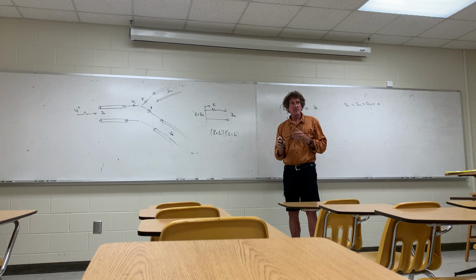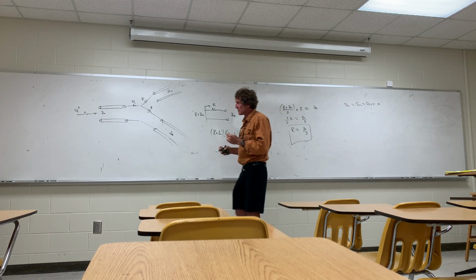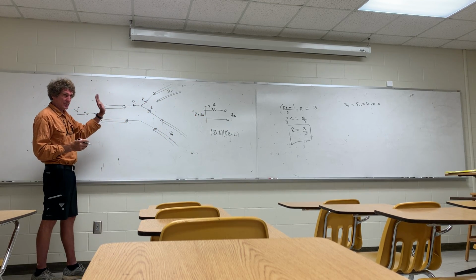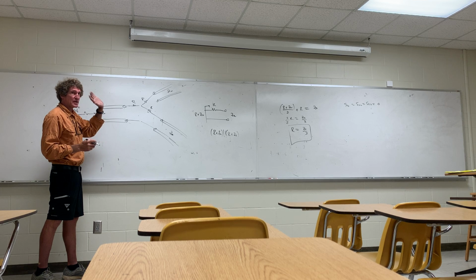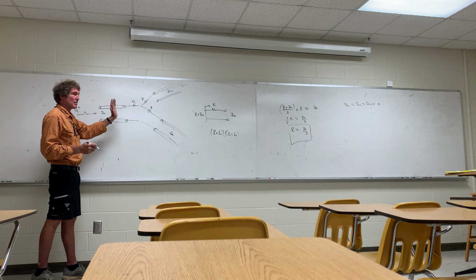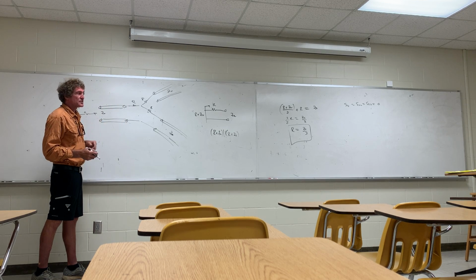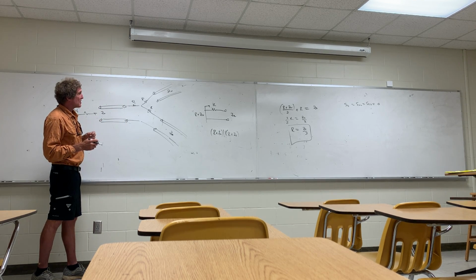Because the goal of this thing is to make sure there's no reflected energy. That's the whole deal. And by the way, that's a very important deal. You don't ever want reflected energy. It causes nothing but problems. Reflected power. So you make sure S11, S22, and S33 are 0.